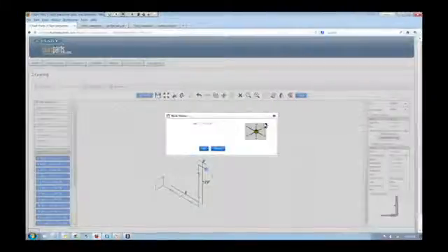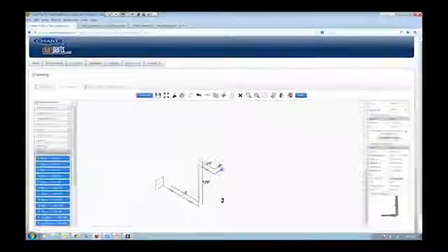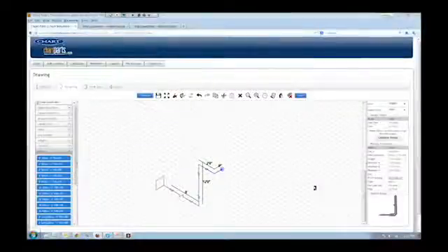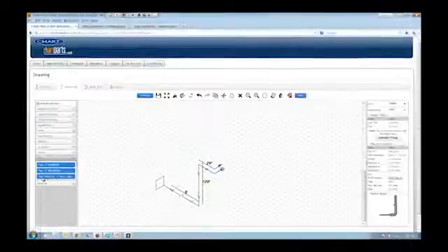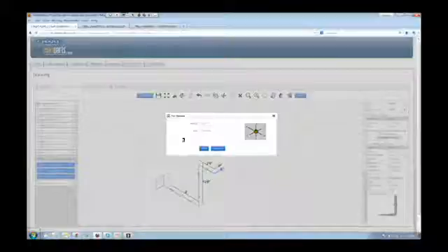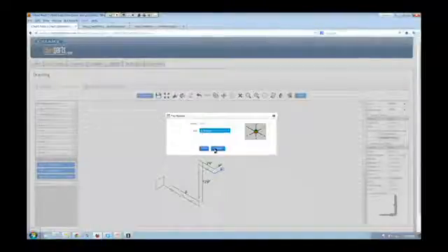Okay, and that's in the positive Y direction. Somehow it knew that. Okay. Now I've got a T that I'm putting in. Item 4 is a T, female, male, male T. So I scroll down to my T selection, female, male, male T, and I want that to drop down in the negative Z direction. Okay, so it did that.